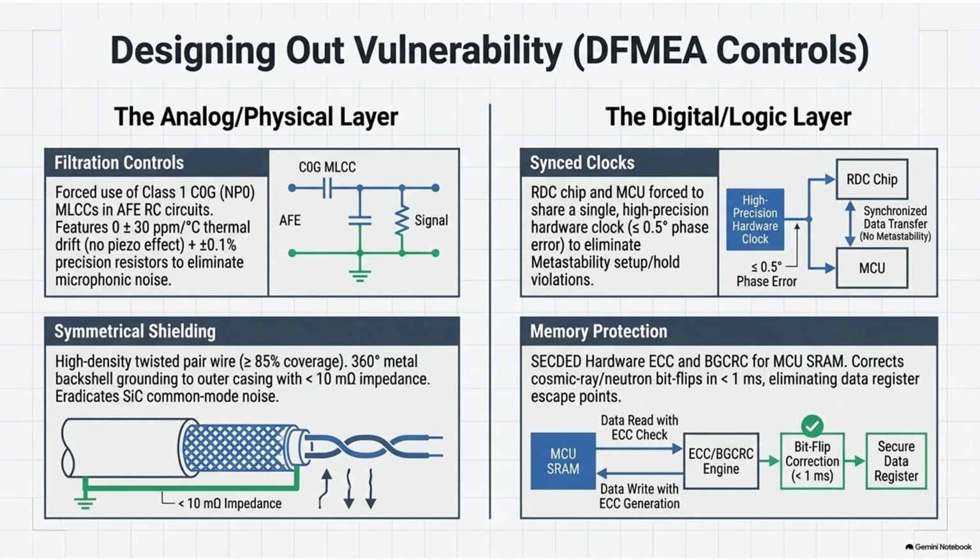Another physical connection vulnerability is the crimping of the metal terminals to the wires. If a crimp is too loose, the wire can pull out or suffer high contact resistance. And if it's too tight, the mechanical deformation can break the internal copper strands. So the process controls utilize dynamic crimp monitoring. The crimping presses are equipped with precision force and displacement sensors.